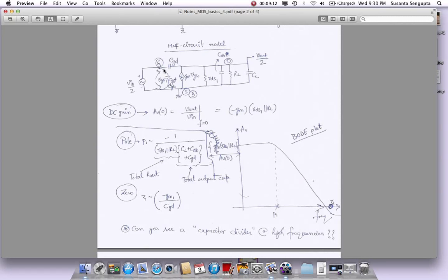So if you write the equation that the current going this way is actually coming this way and none of it goes out, such that the output is 0, you can easily find it as V in divided by the impedance, which is V in times S times CGD. That gives you the current here, and you turn all that current around and say all of it goes to GM times VGS, this controlled current source, and nothing goes here. So when you put the equation, you will see the 0 is caused at GM1 or GM here.